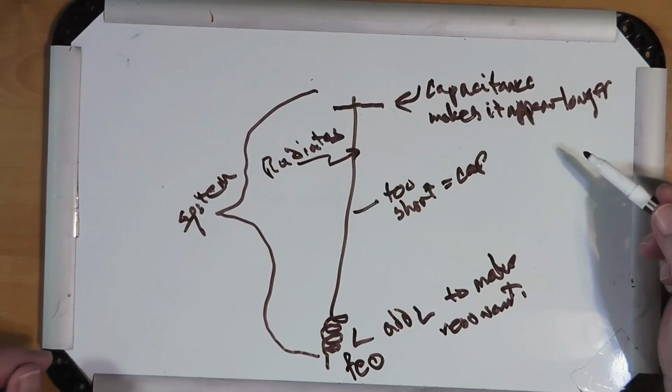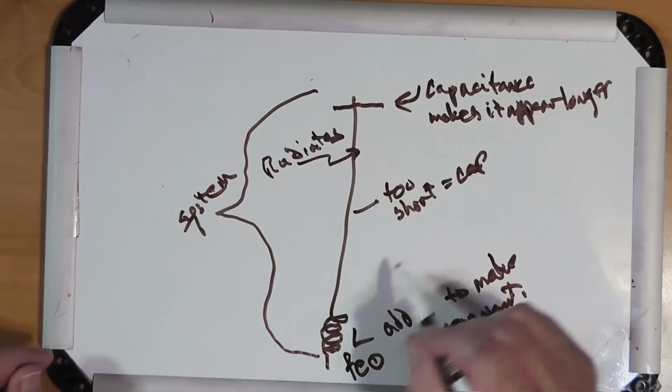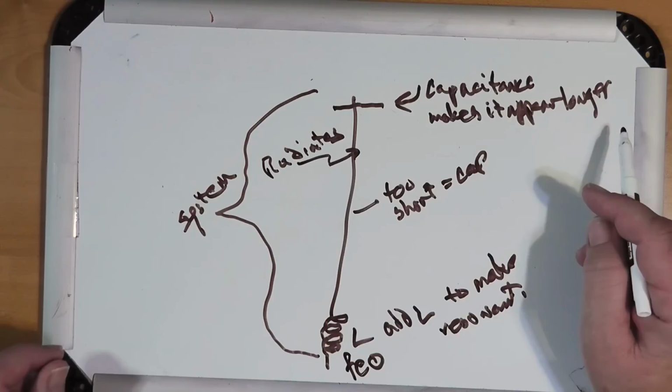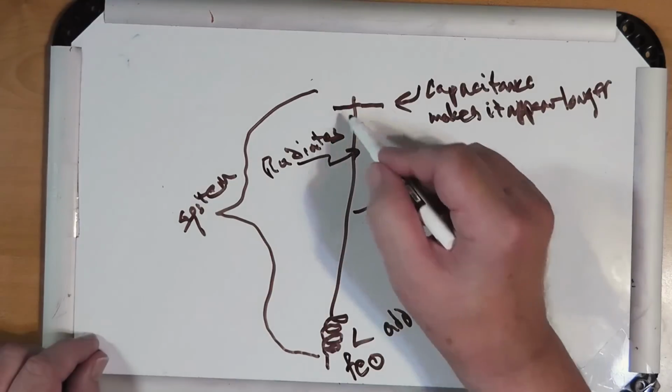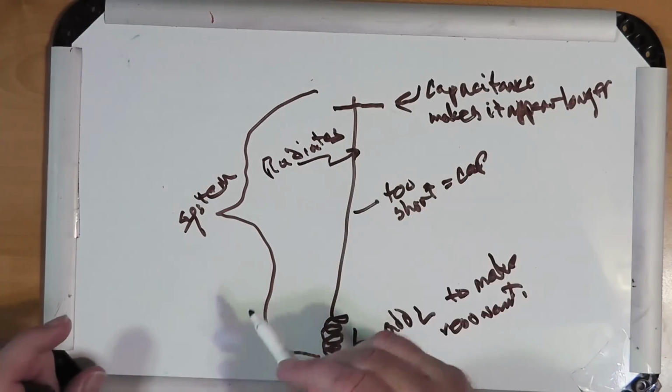And the current in here, you have to think of not as a waveform, but as, well, if you're CW, steady AC voltage. Everything is RF. It's AC. There's no DC in here. Okay? So if you go too far with the capacitor on the top and too far with the loading coil on the bottom, you can actually get this thing down to a point,